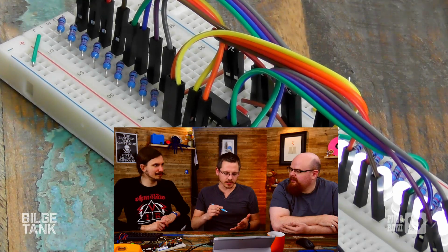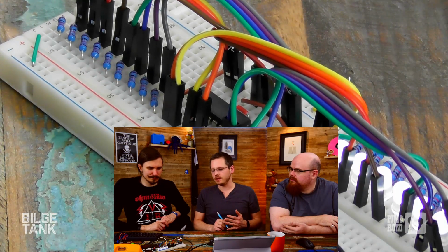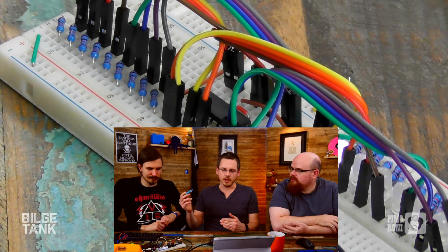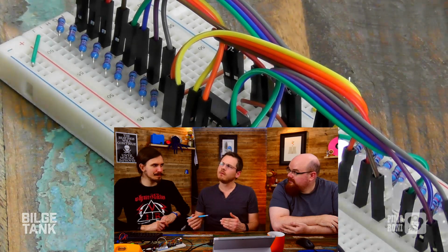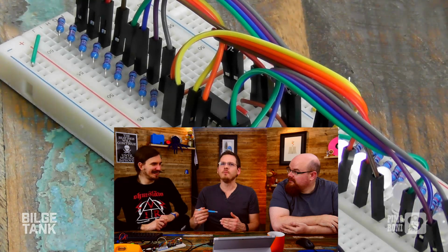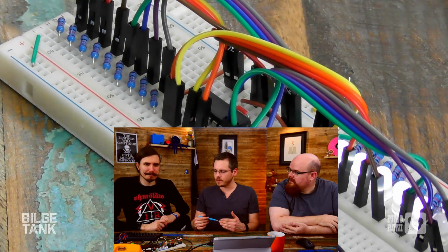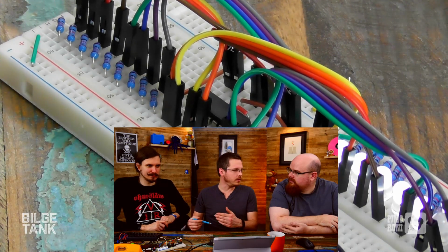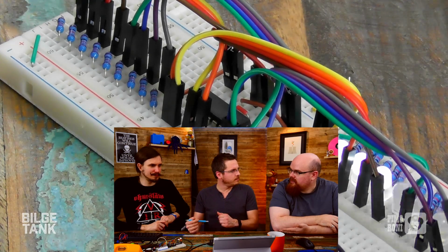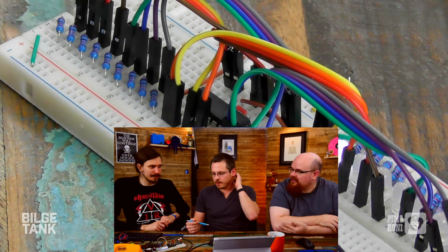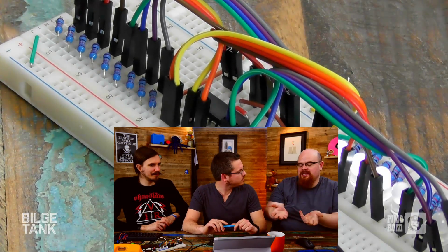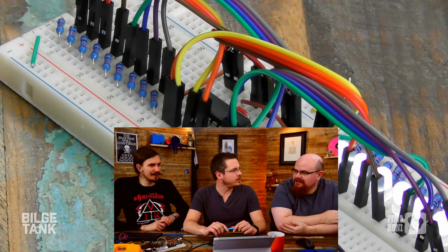So if we put 2 volts into the positive terminal of the comparator, and 3 volts into the negative terminal, then our output will be low, and the other way around it will be high. So it's as simple as that. That's very basic, one bit of resolution. In fact, it's no resolution really, because it's just which one of these is higher. It's almost logic.